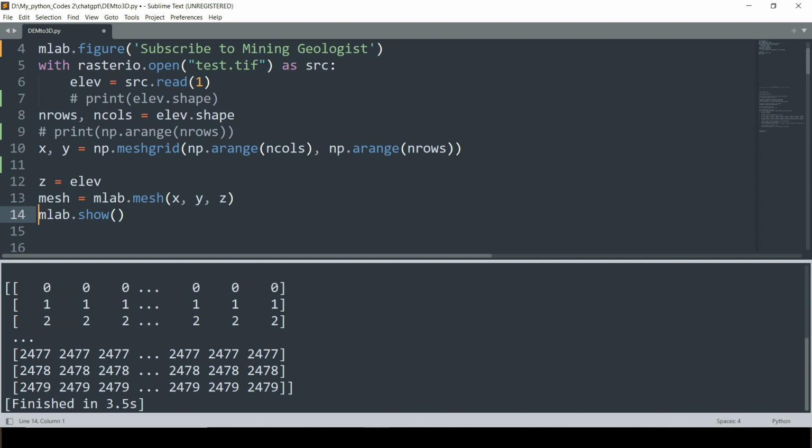Okay. So, one simple piece of advice when you're trying to use this method: I really advise you not to use it directly if you download a DEM from USGS, because it's going to be a really large data set with a lot of variation. And especially if it contains a lot of pixels, you're not going to see something that you like. So I really advise you to use the method that I showed you in the Python DEM tutorial, or you can download your own DEM and clip it in GIS software so you have a smaller area, and that way it's going to look better.